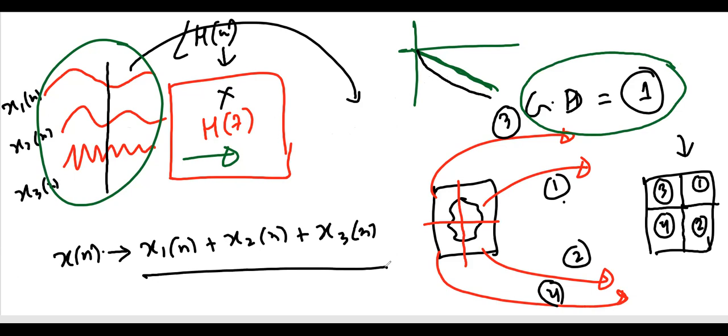That makes a nonlinear relation between signal number 1, 2, and 3, and that's why your life becomes very difficult. I will talk about this more with some examples: how this nonlinear phase response makes our life difficult, and how to solve that problem. So where is the nonlinear phase introduced? By IIR type filters. So how do we tackle this problem?